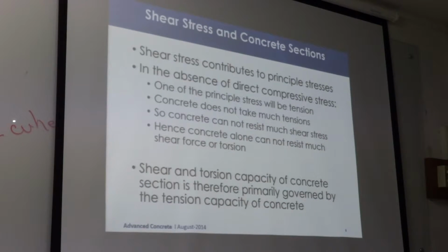Combined shear and axial stresses have a limit, which is a principal stress, right? Out of that, some part can be shear, some part can be axial. If axial is more, less will be left for shear. And when you reach maximum axial, zero shear automatically.